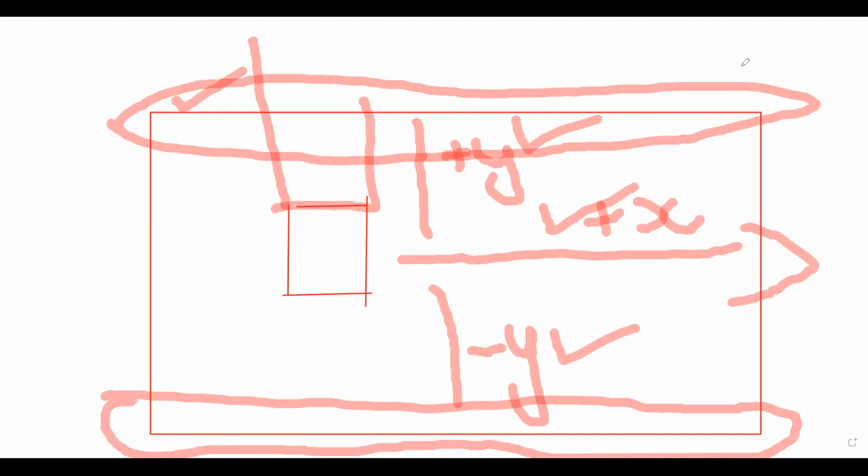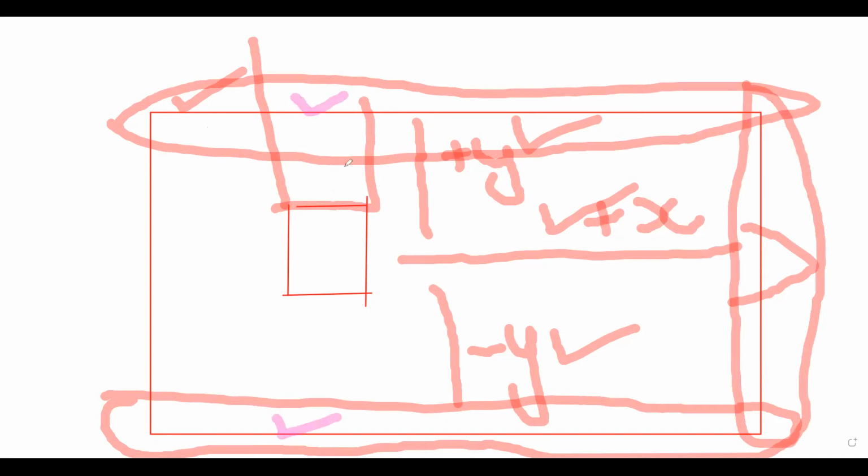So you have to increase its value, and you have to also increase the value of this. These both are walls, and this one was your outlet. You have to increase the extent. For example, this upper one is 30, from this point to this point minus 30 at the bottom, and from this, it might be 50 or 60. Change its extent. When you change these things, it will automatically affect your simulation and your results will become 100% accurate.